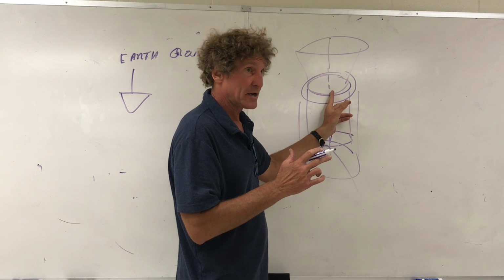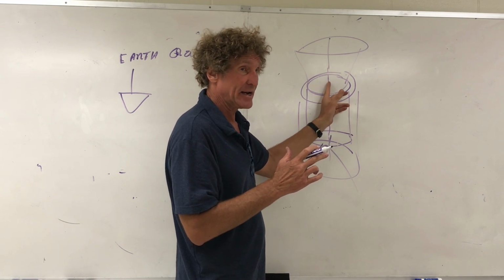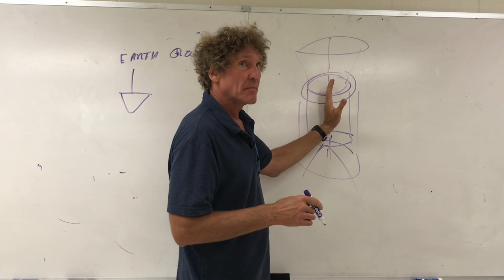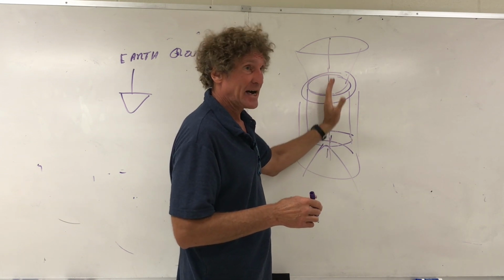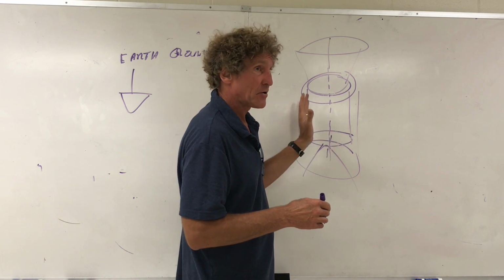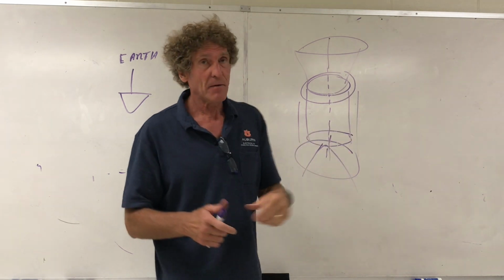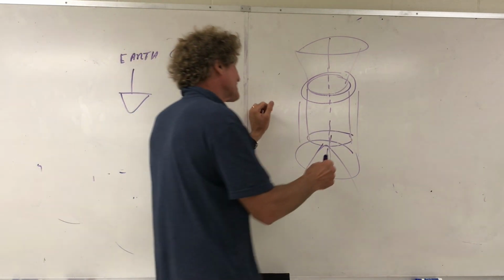If there's an arc, the current will be sustained. That's why you can't have a high voltage fuse with just a thin wire. Even though that wire may sever, its ionized region will continue the current, just like a lightning bolt. So we filled it with sand, and then we hooked it to ground. Now, sorry, this is the high voltage fuse.